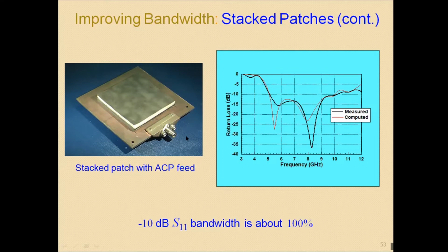For the testing, first we have to test the antenna with the help of the network analyzer. The network analyzer will measure all the S parameters. The S parameter that can be measured for the antenna is S11. The antenna is a single port antenna, so there will be only one S parameter. S11 will be the S parameter for the antenna.